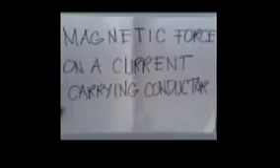Magnetic force on a current-carrying conductor. Now, what makes an electric motor work? Within a motor are conductors that carry currents, as well as magnets that exert forces on the moving charges. Hence, there is a magnetic force along the length of each current-carrying conductor, and these forces make the motor turn. Now, we can compute the force on the current-carrying conductor starting with the magnitude of the magnetic force, which is F equal to q V cross B for a single moving charge.